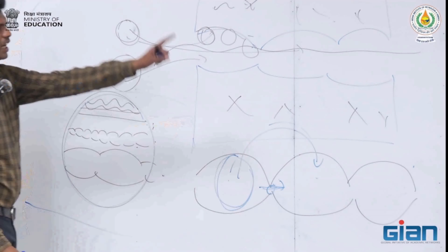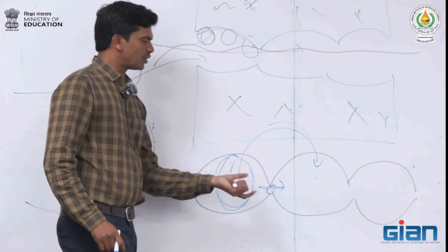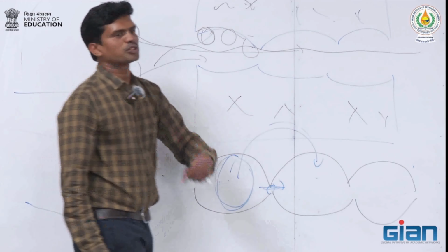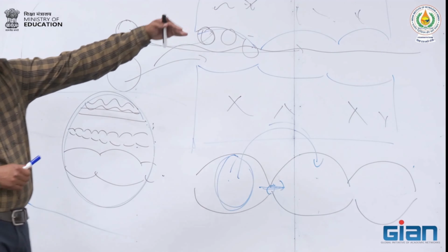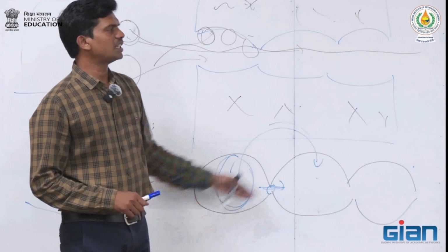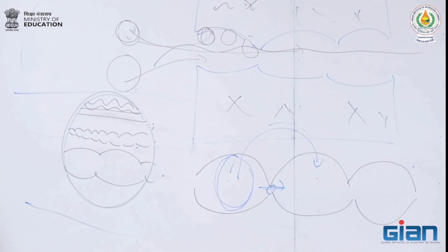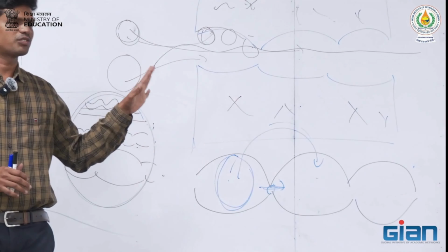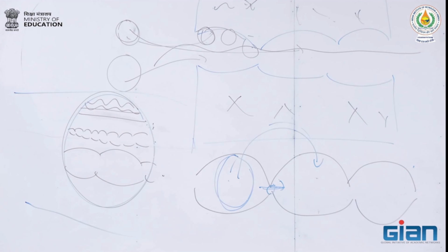So we have to check what the pore size distribution is. What is the biggest size of the pore? What is the smallest size of the pore? We need to cross check everything before selecting these materials. That's what we are talking about with diffusion rates. This molecular sieving property does not allow some molecules through. And we always look into surface area per unit volume, because that's what we want. More surface area is wanted for adsorption.